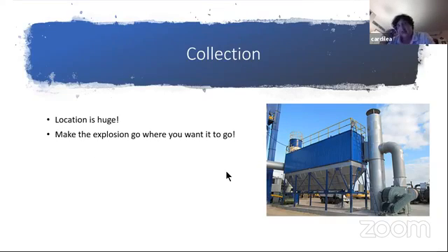If you have a properly sized collector, they do explode sometimes, it just happens, but they're designed to do that. So you'll lose a vent. It's better to get a new vent than it is to have to replace lots of pieces of equipment. And they're designed literally to not deform this. They're designed to protect the dust collector, those vents.